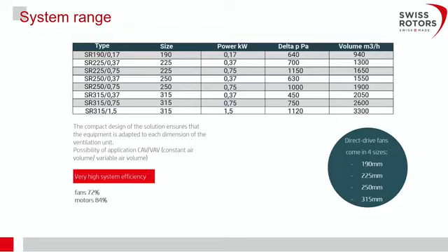Of course, you can have higher pressure drops and higher static pressure, but then the efficiency will be a bit lower because it will not be working in the optimum operating area. So that's the idea which we have, and as you know, somebody else is also introducing and using these fan array systems.